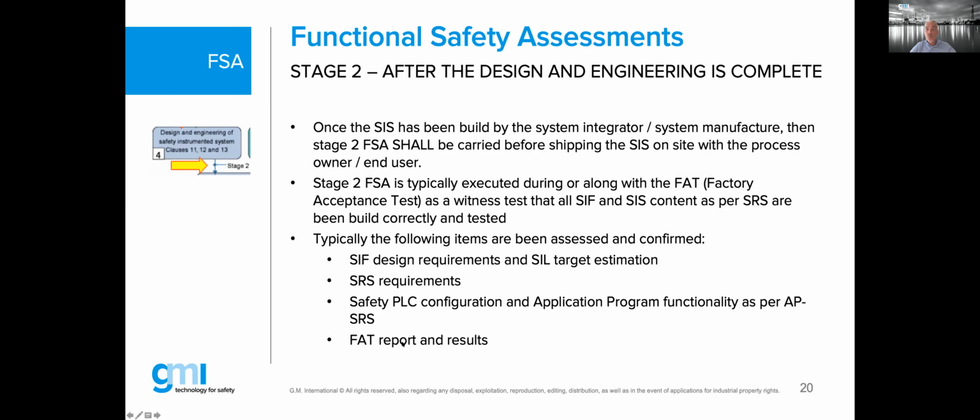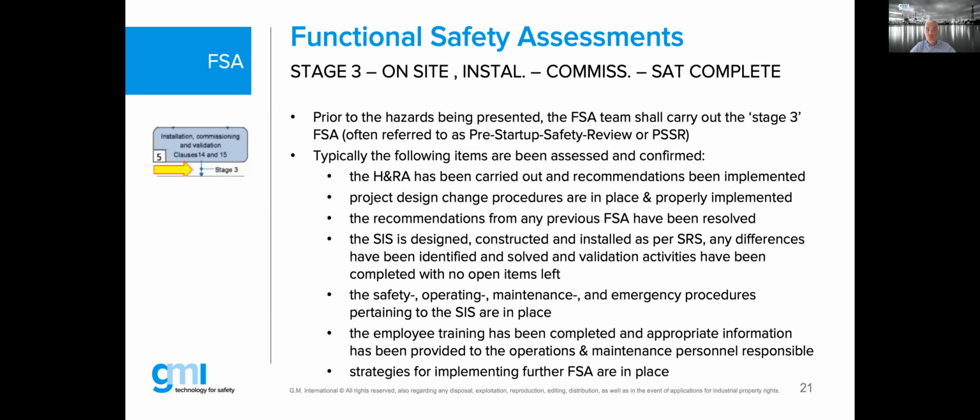And a small hint on the report, we also want to see, when there is an open item, punch item, open list, whatever you call them, that those are closed before the system is shipped. Not waiting until it is shipped on site and then trying to solve some of those items. We want to see that as expert witness before it ships from the factory to site.